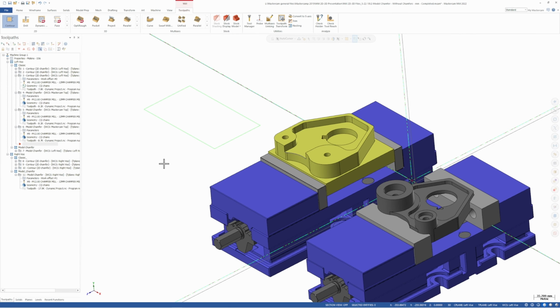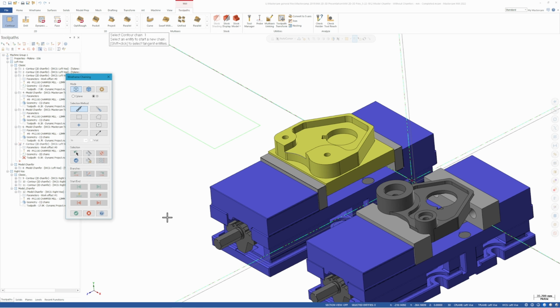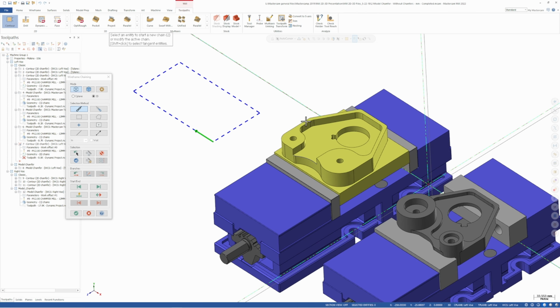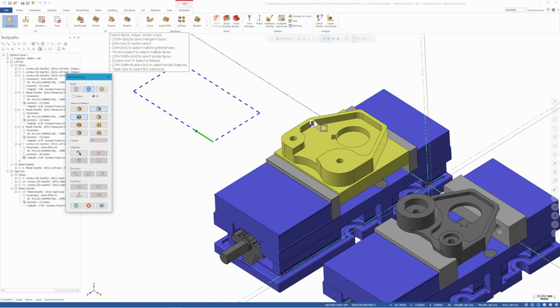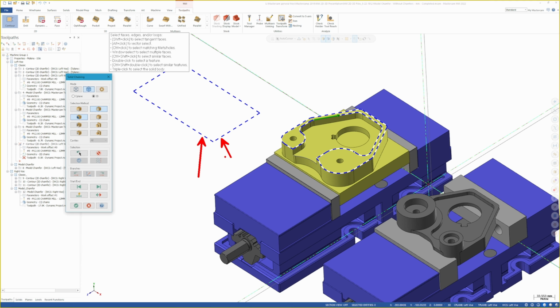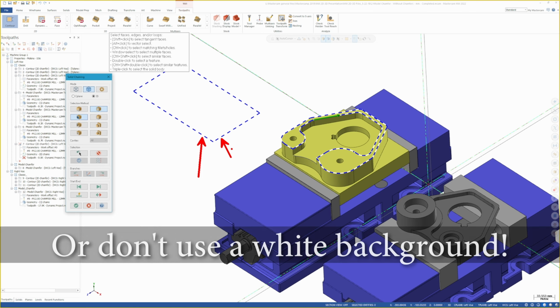One thing to be aware of here, I'm using a white background and I've played with the chain highlighting options, the chain highlighting colors. You can see the alternate color for that chain selection, like we did on the solid model. It's using a white secondary color. So unfortunately on the chain, you can see that I've kind of lost part of the highlighting. As far as I can see, there's no way to change that secondary color. So if you are using some alternative colors here for chain highlighting, you might need to experiment with them to see if any of them give you a different secondary color.